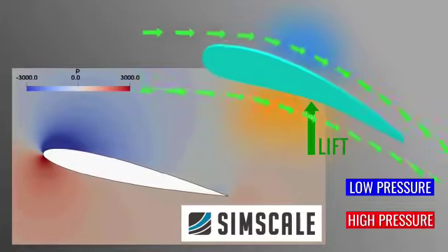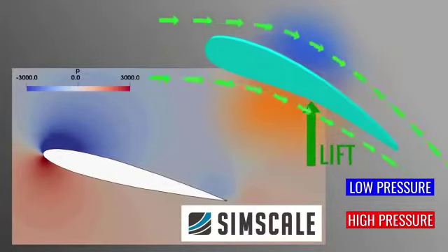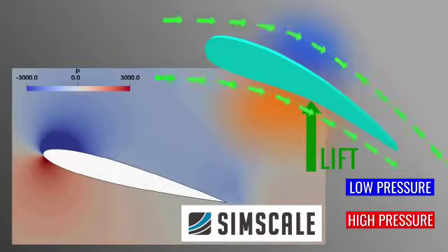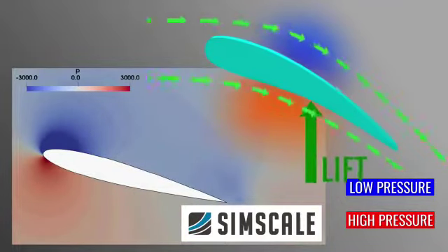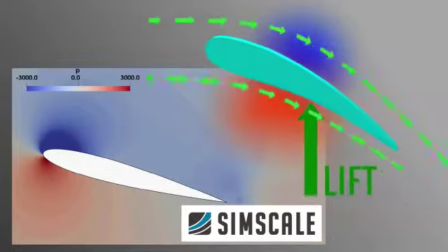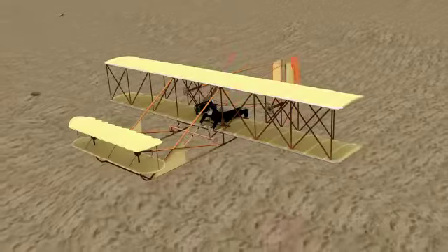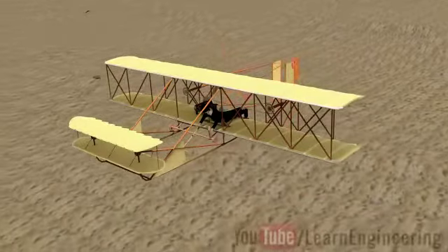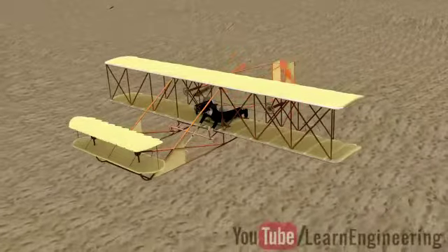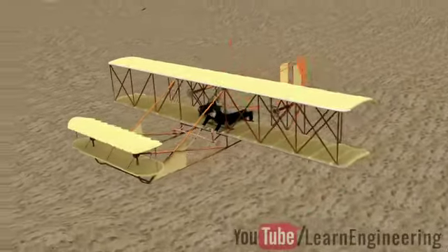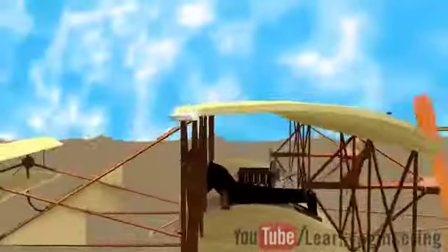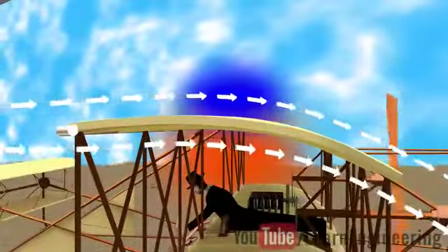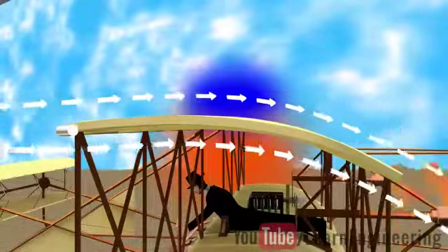Generally, the higher the angle of attack, the greater will be the downwash and therefore the lift force. A greater airspeed also increases the lift force significantly. Interestingly, in mankind's first successful flight, the Wright Flyer also made use of this same airfoil principle. Even though their airfoils were a simple curved shape, it was sufficient to produce a good downwash.